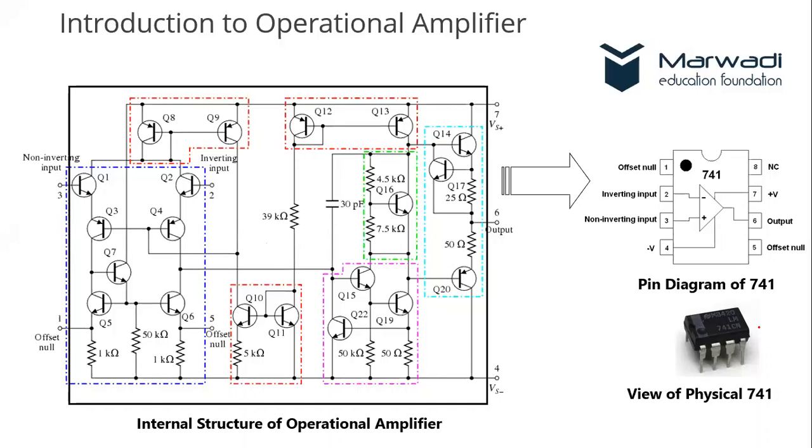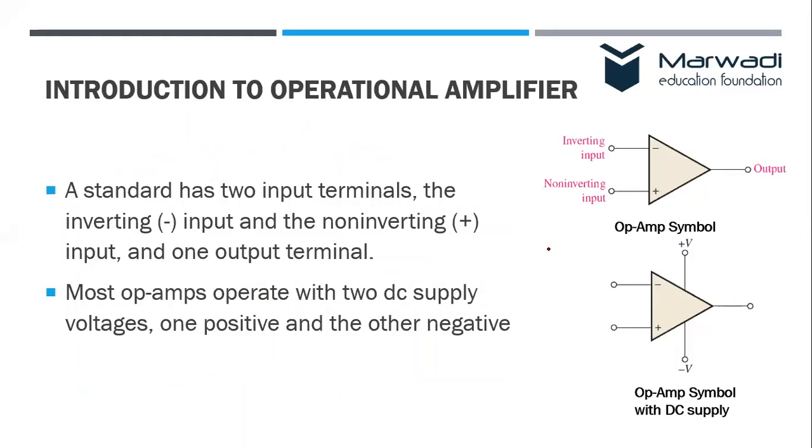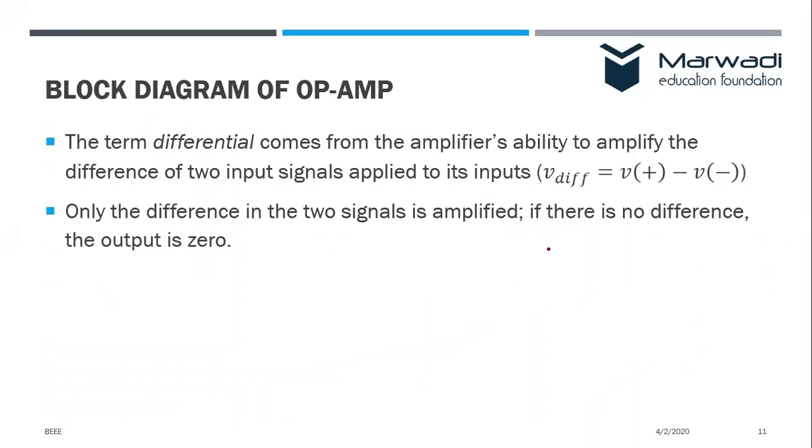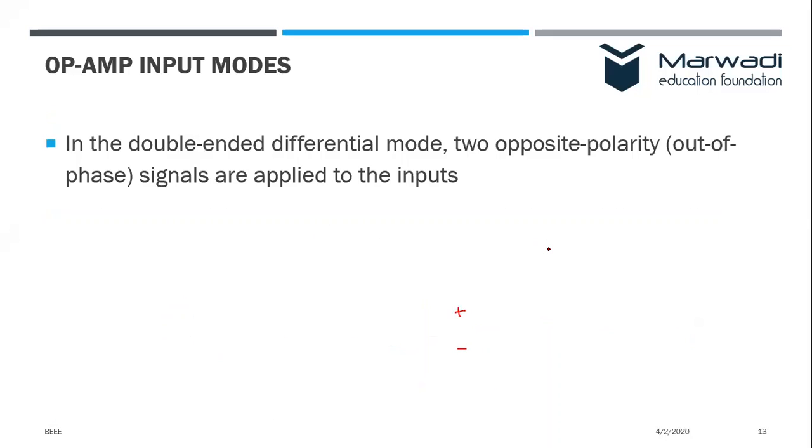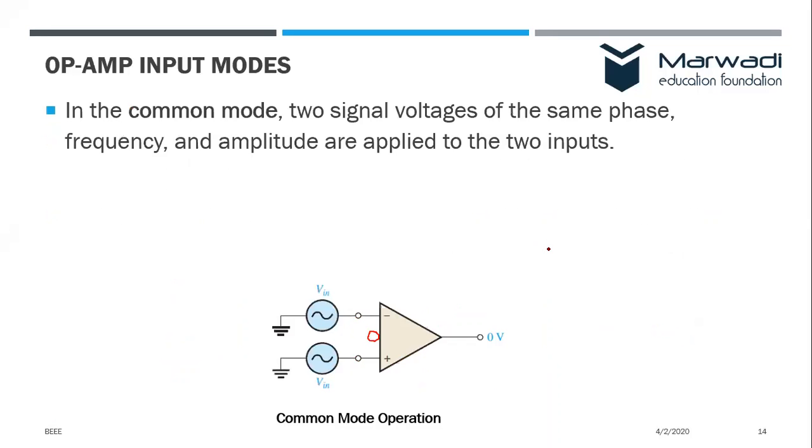Now if external noise is affecting, then it will affect here and here in the same way, right? It may not happen that they will be affected in a different way. It is going to affect both of them, and if it affects both of them, then they will cancel out each other, and the output of the noise will be 0. So this is called common mode rejection, right? And it is good actually,